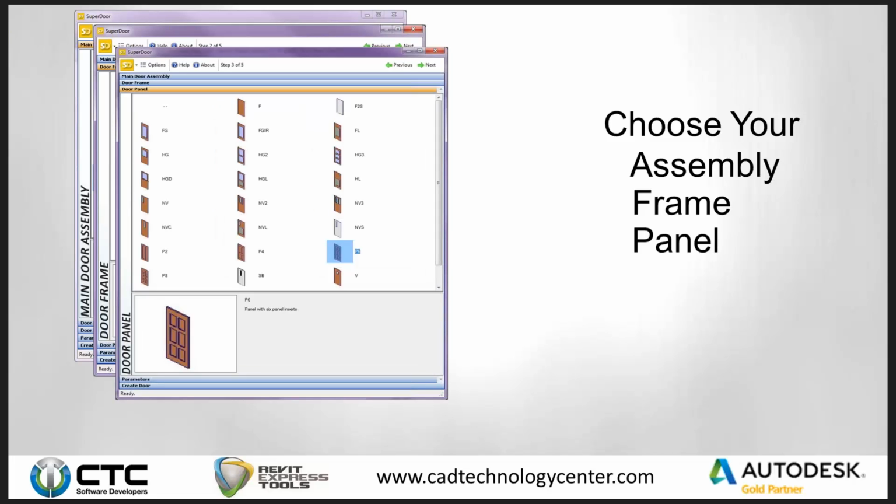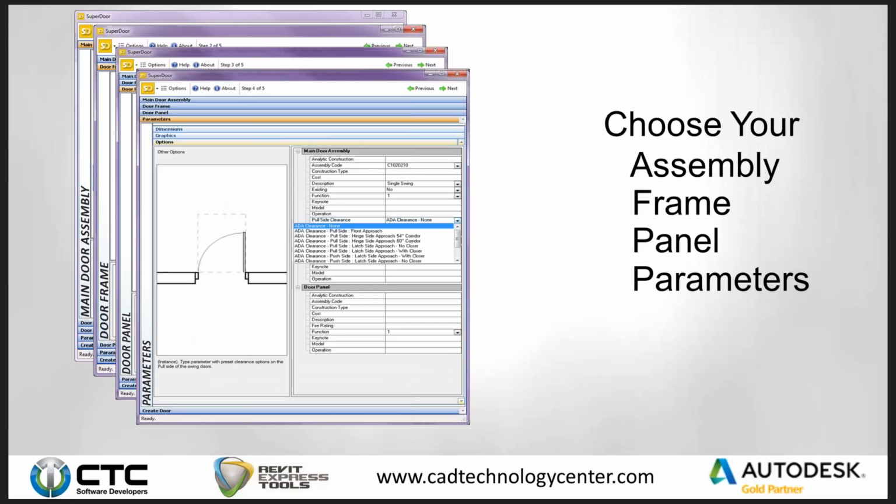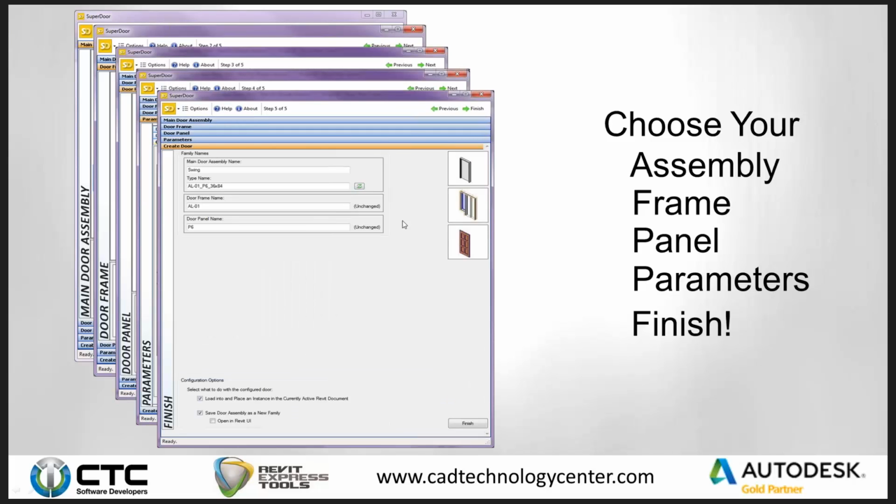And then the fourth step, you have an option to configure any of the parameters that exist within that door family. So you can change things like the width, or in the example here, you can do things like configure an ADA clearance for that door. The last step is going to be to verify the naming convention that you want to use, and then go ahead and load that door into your project, or save it out to a library for later use. So let's toggle over to Revit and just take a quick spin through the SuperDoor interface.